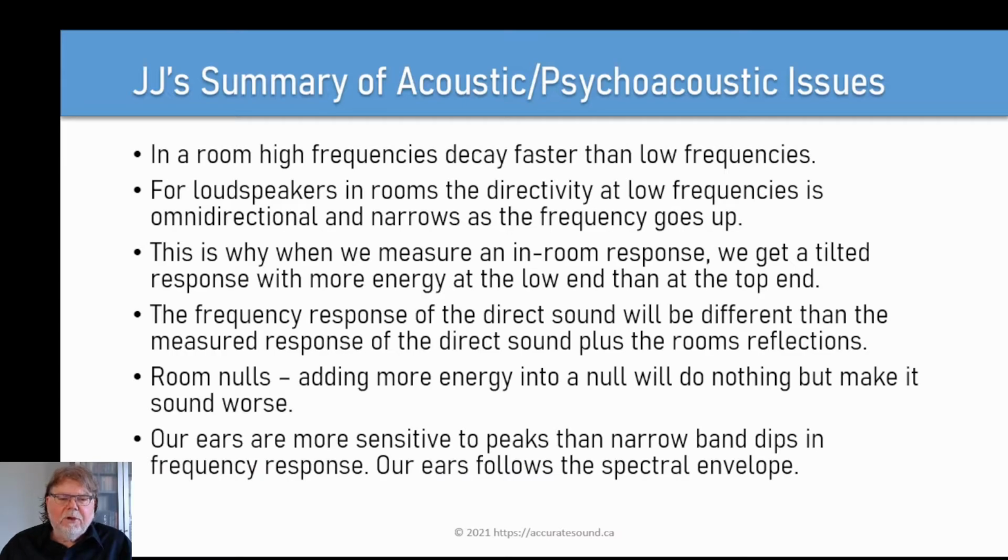The frequency response of the direct sound will be different than the measured response of the direct sound plus the room reflections. When it comes to room nulls, adding more energy into a null will do nothing but make it sound worse. Our ears are more sensitive to peaks than narrow band dips in frequency response, and our ears follow the spectral envelope.